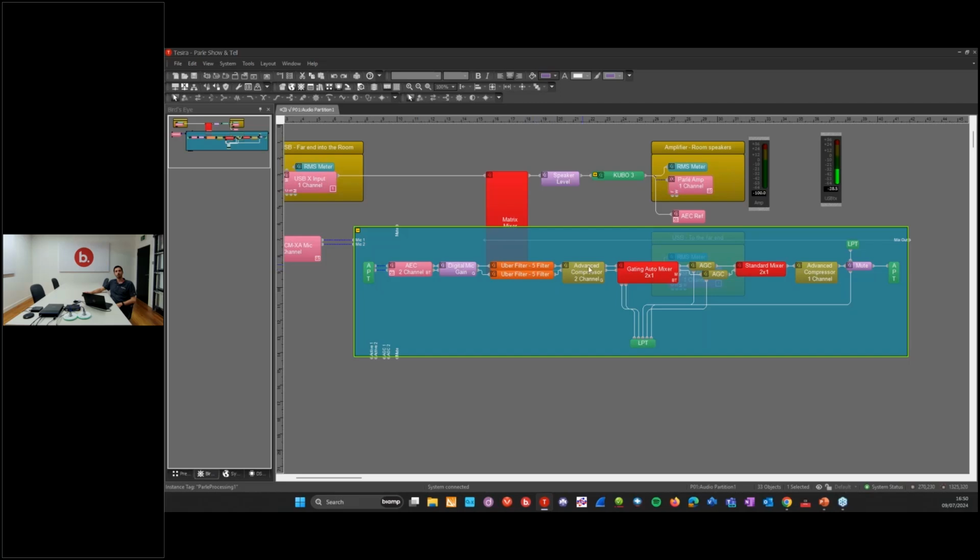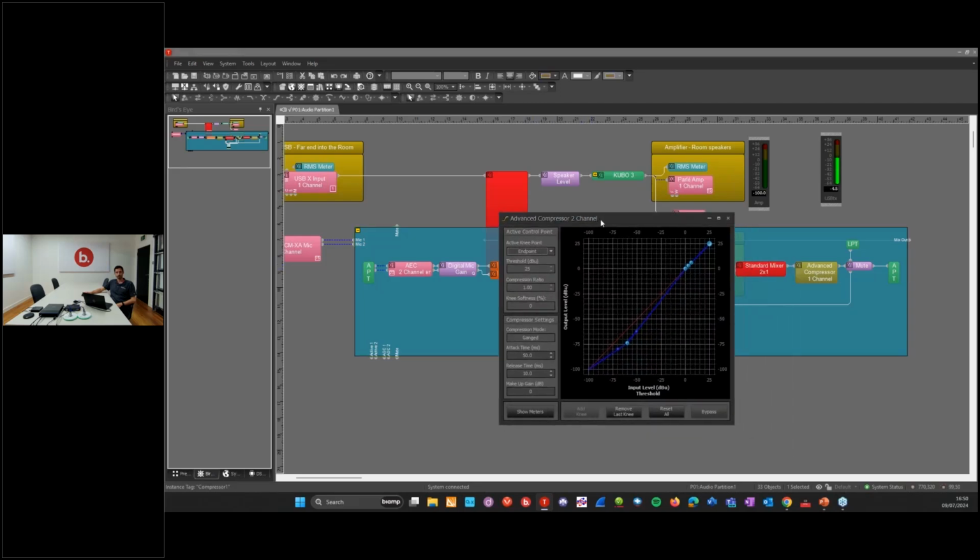Following the filter block, we have an advanced compressor, and what this is doing is actually working in reverse. If I go quiet, you'll see on the meters there that they're pushing the signal level down. Anything below this threshold here is going to be attenuated at the given ratio. So when I go quiet, and then as I begin to speak, more of the signal is allowed through. What this essentially is, is a soft noise gate. When no one is speaking, any ambient noise in the room is just going to be pushed down and give a nicer experience at the far end.